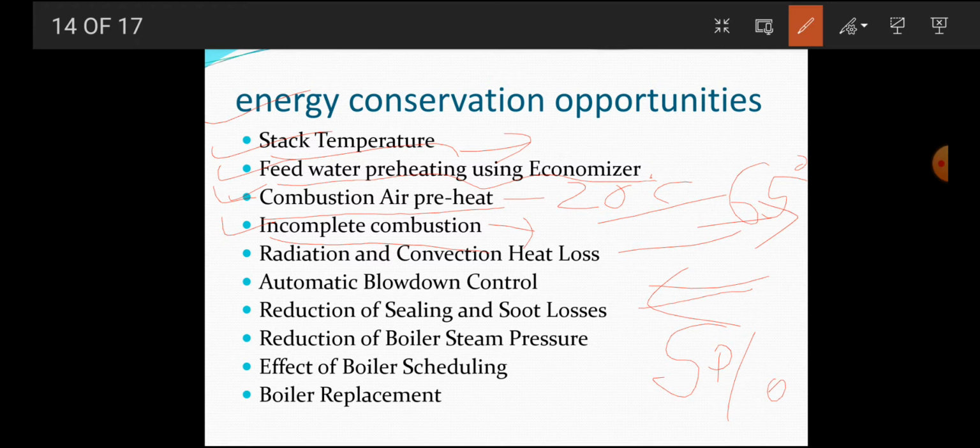If combustion has not taken place 100%, then unburnt carbon comprises a very big loss. It occurs as grit carryover, and carbon in ash may amount to more than 2% of the heat supplied to the boiler. So 2% of extra heat may need to be supplied to the boiler.